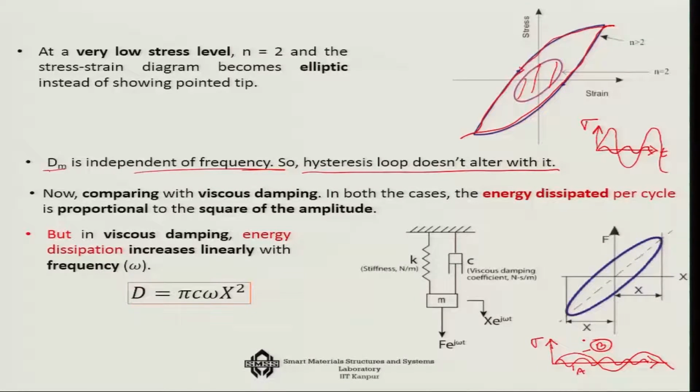And I told you earlier that for viscoelastic material, if the frequency changes, let us say omega, then you would see that the modulus of elasticity, for example, changes very much. Low frequency, remember, is always like a high temperature situation, and high frequency always behaves like a low temperature situation. So, that is the way it is going to behave, and since the modulus of elasticity is changing, everything corresponding to that will be changing.